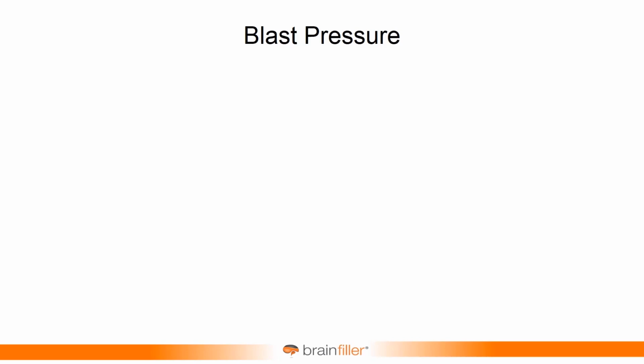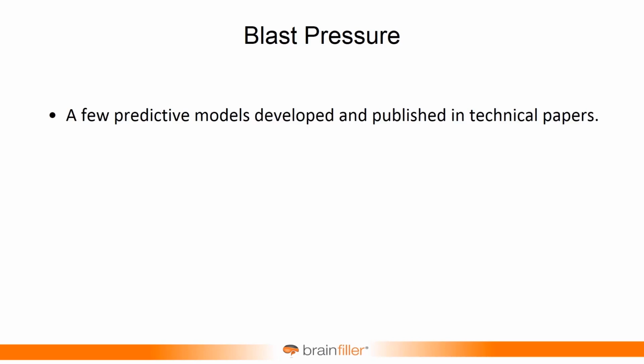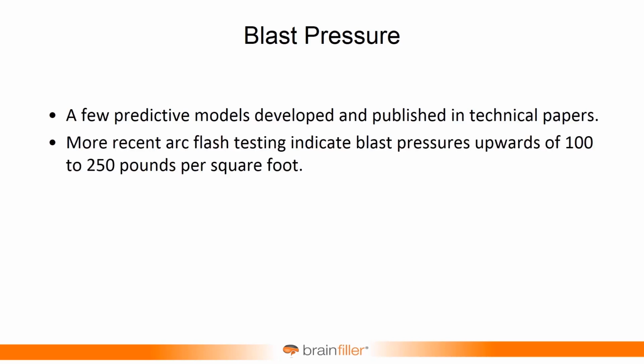The blast pressure is still something that we're scratching our heads over. The thought is, yes, if there's a really significant arc flash, and it's really more short circuit dependent, you can have a pretty significant blast pressure. But the measurements are showing that the pressure is somewhere between 100 and 250 pounds per square foot. I mean, it's significant, absolutely. It can knock you off a ladder, off a scaffold, do all kinds of things like that.